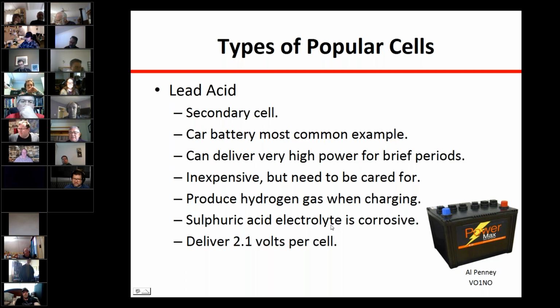And Isaac, that's a bit of an old wives' tale about keeping a battery on a concrete floor. What it might be is that usually if you leave it on the concrete floor in your garage, the floor is going to get cold, and therefore the battery loses capacity because it's cold, but it doesn't actually discharge into the floor.